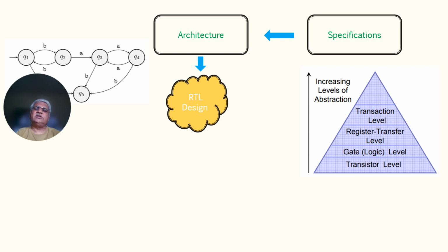Earlier, this used to be a big issue. So we need to use linting tools which will read the RTL code and figure out these simple mistakes so they can be avoided, and there should not be any multi-driven ports.